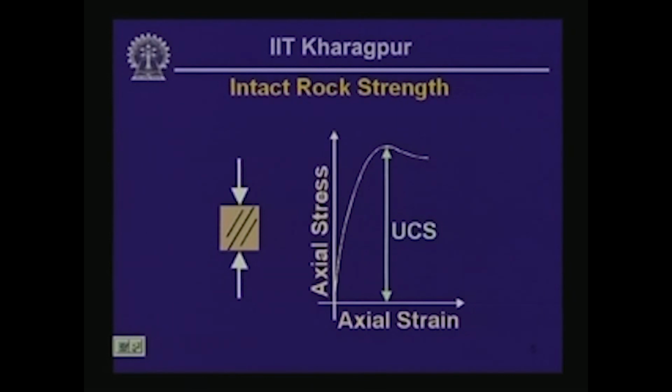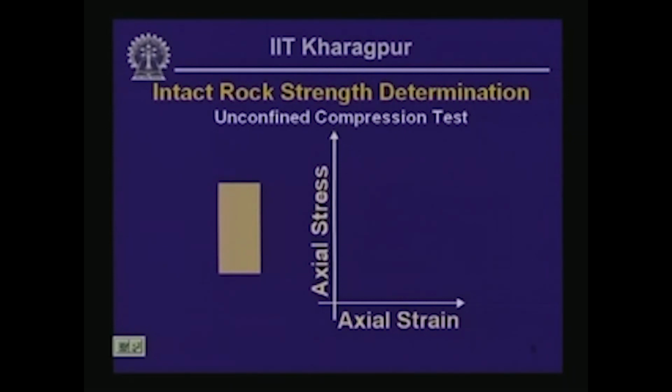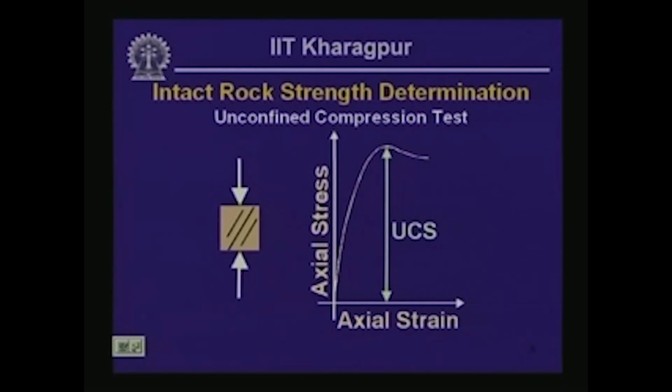Okay. So, then let us move on and let us try to see the sequence once again. In this case I am just going to run the animation, and you just try to observe the shortening of the sample that we are trying to test here, and how the cracks develop within the sample, and the sample goes to the ultimate state of failure. Okay. So, here you go. So, that is how the UCS is conducted.